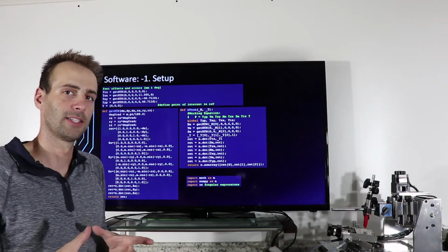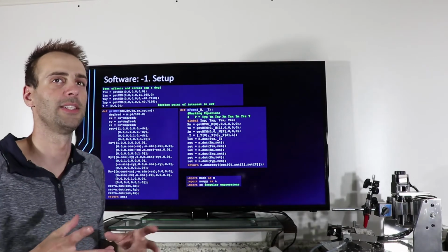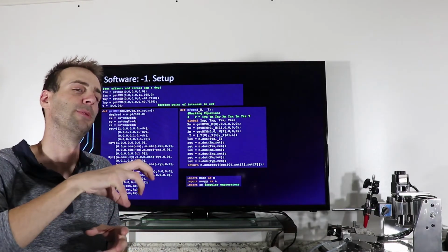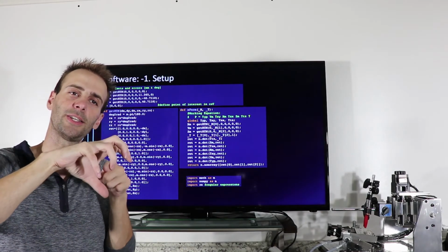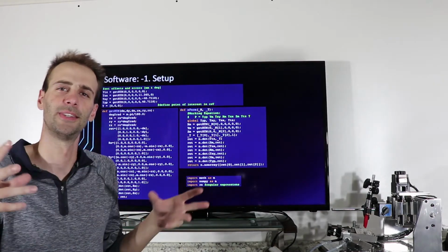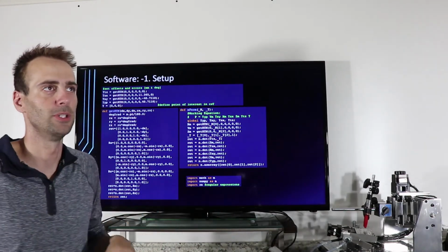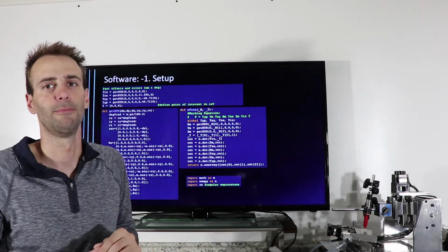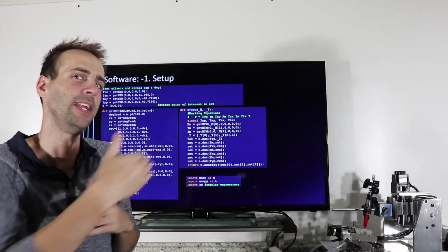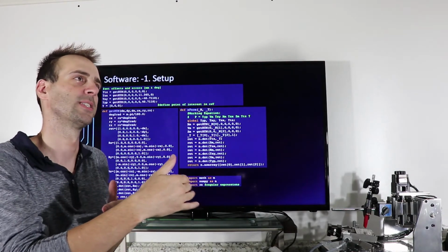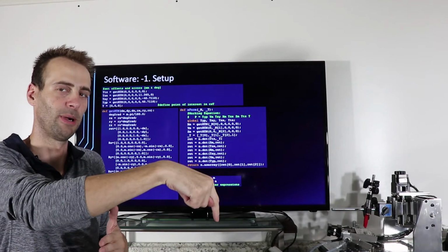Now on 5-axis machining, that's not what you want. You don't put that 0 in there, because if you have, say, a ball nose cutter, I want the edge of the cutter to touch my part, right? What I'll say is most post-processors, like Mastercam and things like that, already compensate for that. So it's where the center of the tool is in part coordinates.